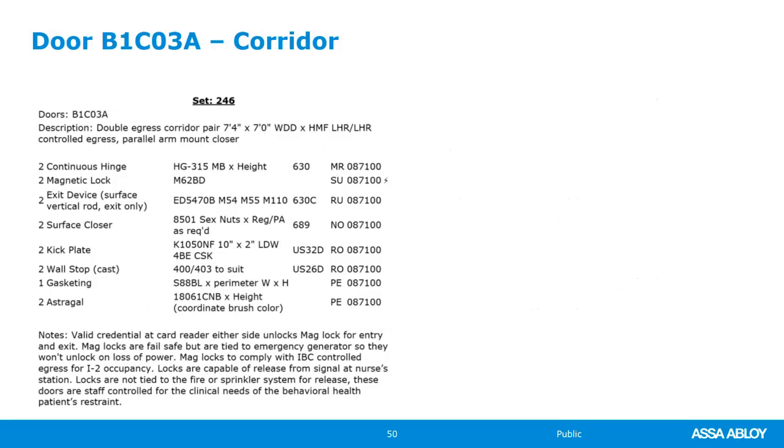I know, for example, Fort Worth, Texas will not allow you to use a maglock anywhere in the city limits, even though the code for the state of Texas that has been adopted is the IBC 2012. They will not allow maglocks in the city of Fort Worth. They've got a written amendment to the code. They won't allow them.